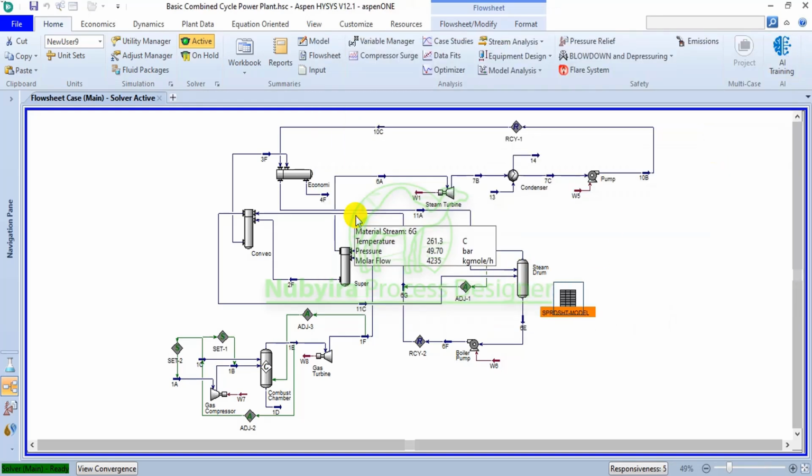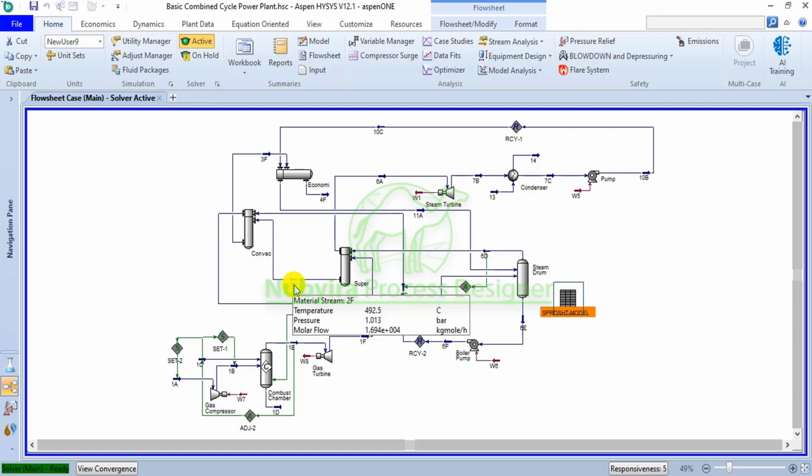Our work today is to size the lines of the steam system, to recommend a certain size of pipeline that will be sufficient to deliver the flow, where there will be no slug flow, no creep flow, the piping pressure drop will be sufficient, and there will be no problem. And as a process engineer, you are tasked with designing pipelines that will be sufficient for the process that you design.